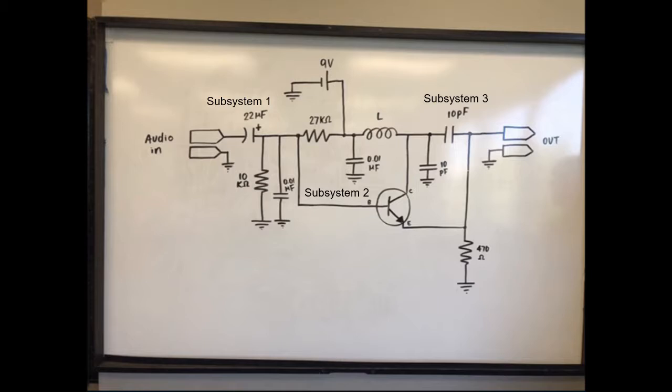The transistor's parasitic capacitance is also utilized, which changes over time due to the audio in signal. This relationship forms the modulating frequency, which modulates the carrier frequency to generate the broadcasted FM signal to be received elsewhere.